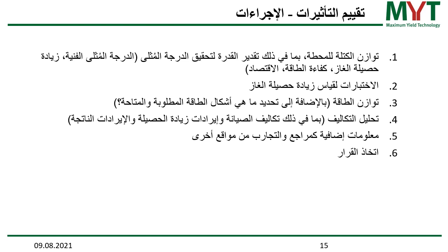So when now transferring this knowledge into an assessment of the effects, you have to do the following steps. First of all, you have to make a mass balance of the plant, and then you should make an estimation for potential optimization. This means you have to check what impact your pretreatment technology would have on your technical material handling operation, and then what potential gas yield increase you can expect.